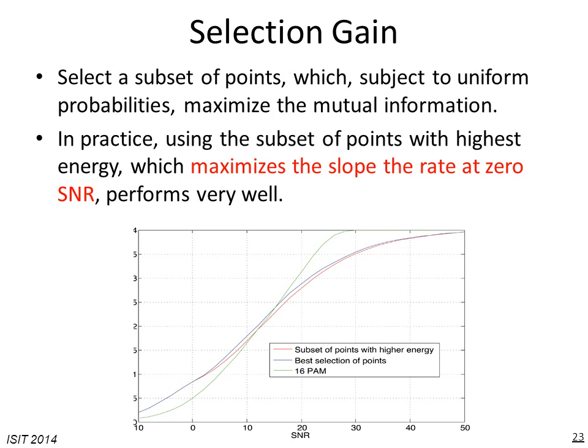So essentially at very low SNR, we'll get a QPSK constellation with a very large norm. And if you have, let's say, X number of possibilities for the channel, it's known from the discussions on multi-user diversity in networks that the selection gain scales with the log of X, the number of possibilities.